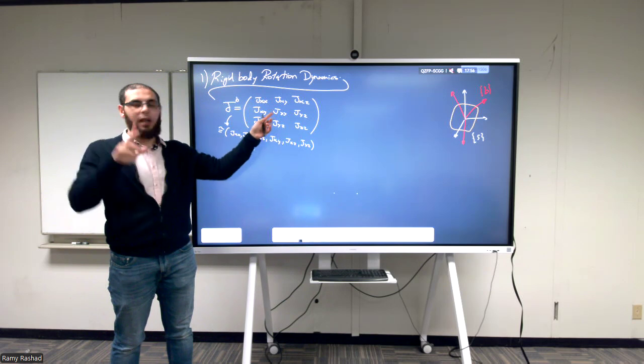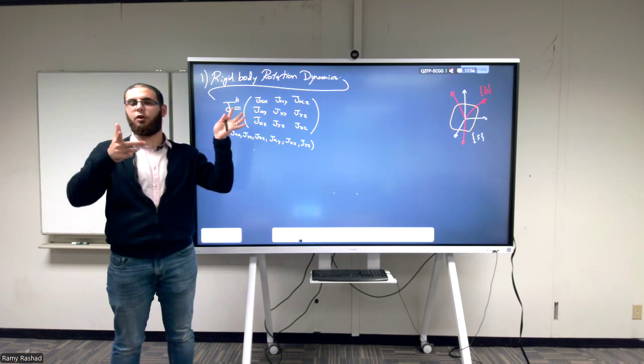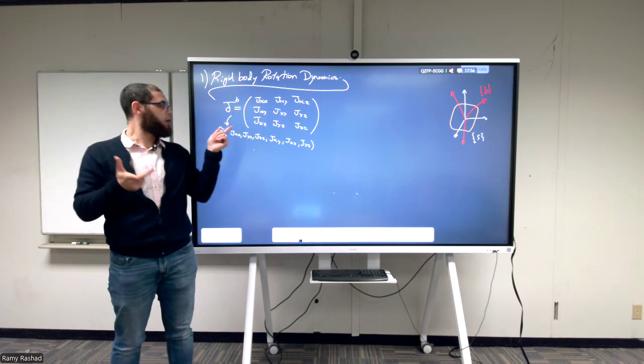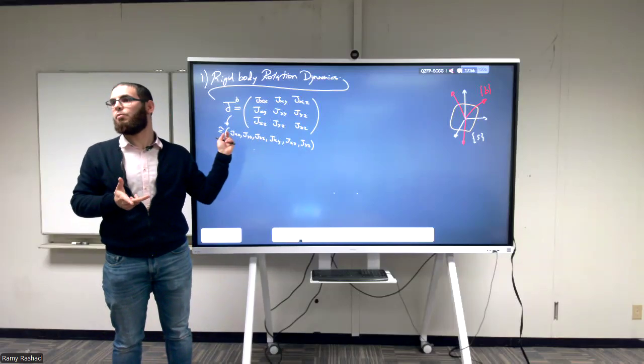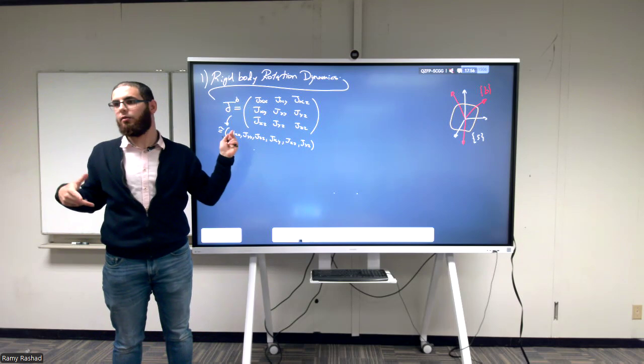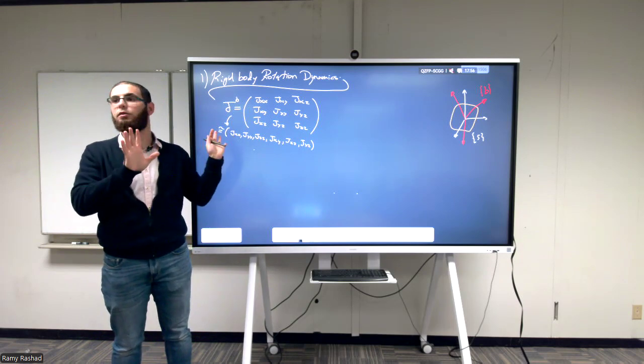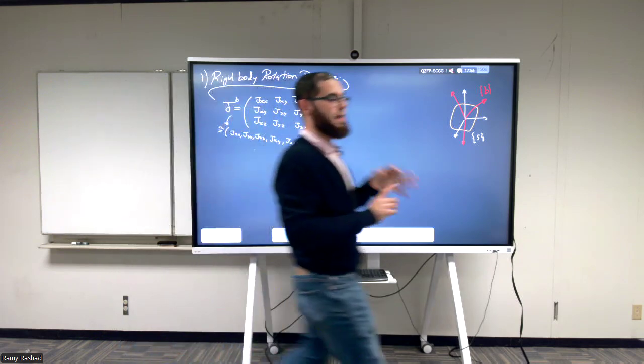And if this frame is aligned in a certain way, along what are known as principal axes of inertia, you get that these 3 numbers are 0, and I get only 3 numbers, which is what you mentioned about being diagonal. Only in this frame. In general, not. So this is the moment of inertia.